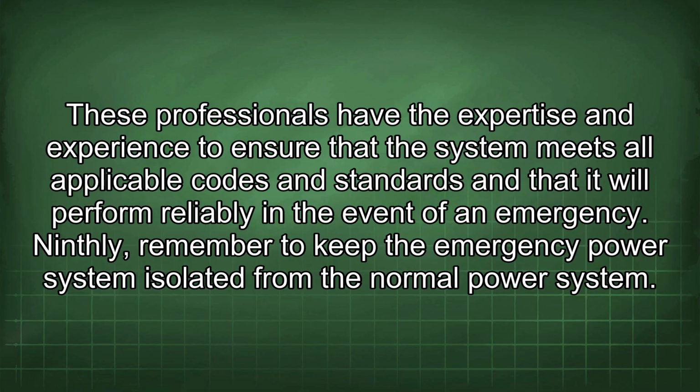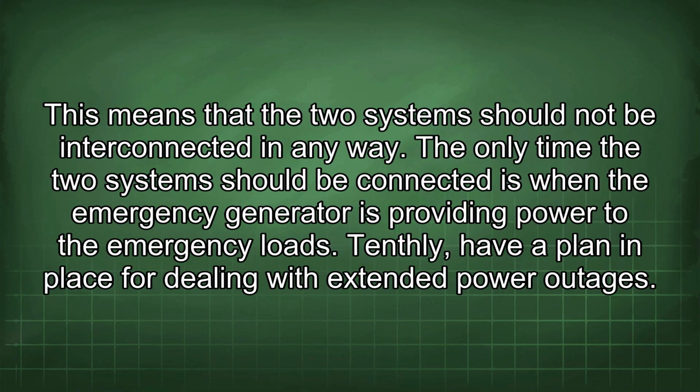Ninthly, remember to keep the emergency power system isolated from the normal power system. This means that the two systems should not be interconnected in any way. The only time the two systems should be connected is when the emergency generator is providing power to the emergency loads.